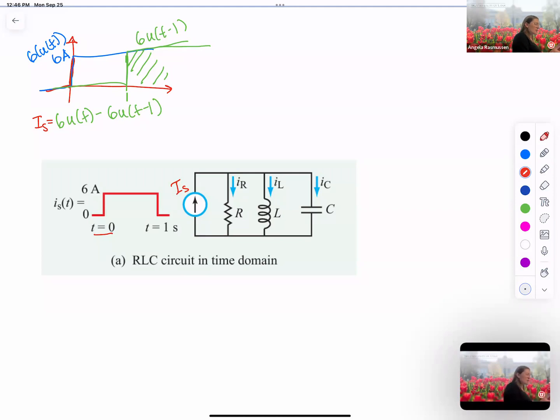This is going to be treated like the resistor, because then it's I times R, and that R value is SL. This one you model like a voltage source, because you can't really do an I times R again. And it doesn't look like a current source, because as far as the voltage across it will be VL. So you want to do voltage drops. That's why it's a voltage source, and this is accounting for that initial value.